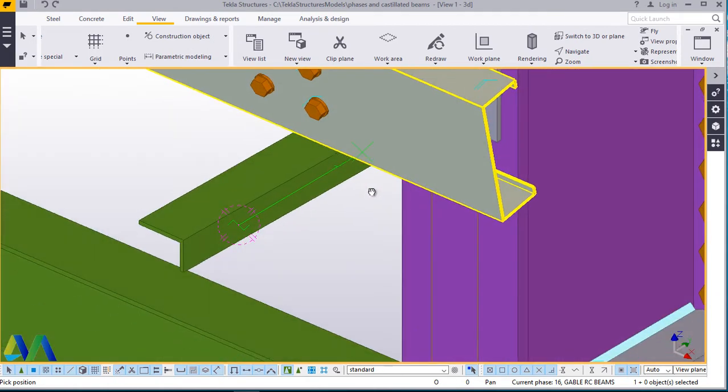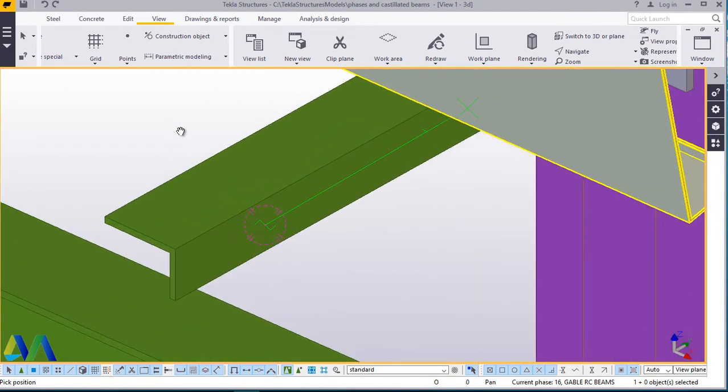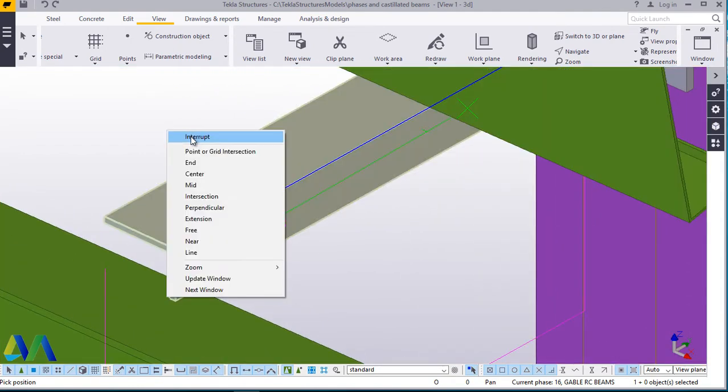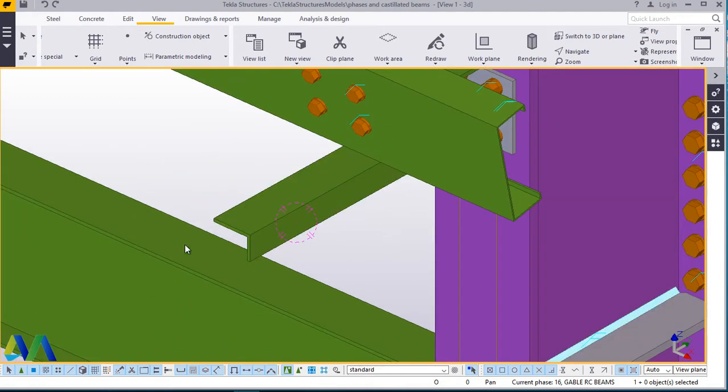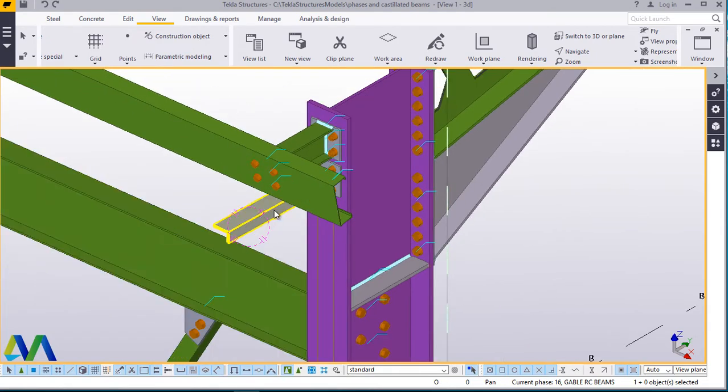Now our gutter will be sitting on top of this support, and the support will be supported further against the beam, against the column. From here we want to populate this. We want to copy this to the next column to allow us to mark the points where we intend to place our first gutter prior to populating it along the full length of the structure or the model.